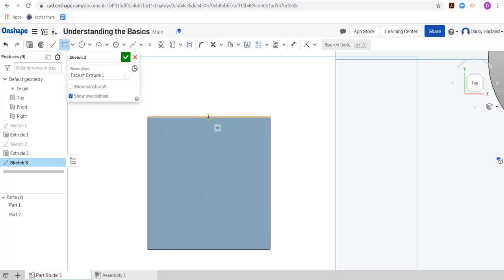So if I find the middle of that edge and then draw a line downwards, you can see if I follow carefully downwards, you can move a little bit side to side, but if you move too much side to side, you lose it. I can move all the way down and it's going to come all the way to the other side. Now if I do that and then do it on this edge as well, find the middle of this line, move across to the center, you'll notice it lines up with the last one that I did. So essentially I've moved it to that center, and I move it to another center, and then I draw down and you'll notice it snaps onto that other center there. So that is the center point of our cube.